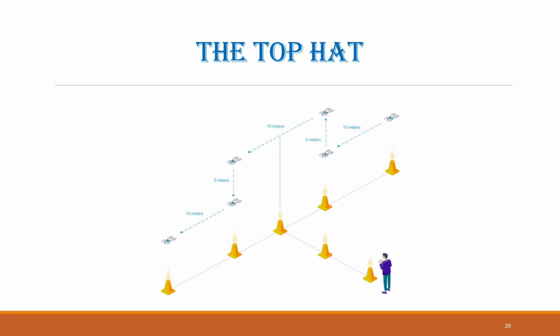The top hat. The top hat maneuver introduces vertical movement combined with precise stopping and positioning. When first attempting this exercise, it is recommended to fly in a tail-in orientation, where the rear of the drone faces you. This makes control inputs more intuitive. Start by positioning the drone either to the left or right side of your flight path, with the rotors at eye level.